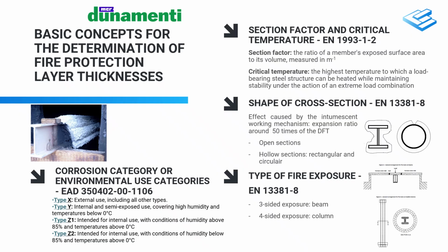To ensure that the surface is filled in during reforming after the crack, a much thicker coating layer is required on circular cross-sections. It causes higher dry layer thicknesses for the circular hollow sections in any kind of solutions and any kind of products. The test standard distinguishes between 3-sided and 4-sided fire exposure.